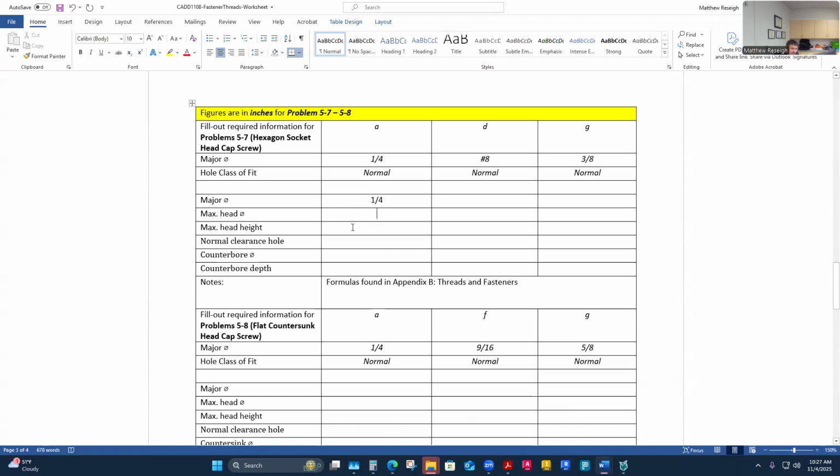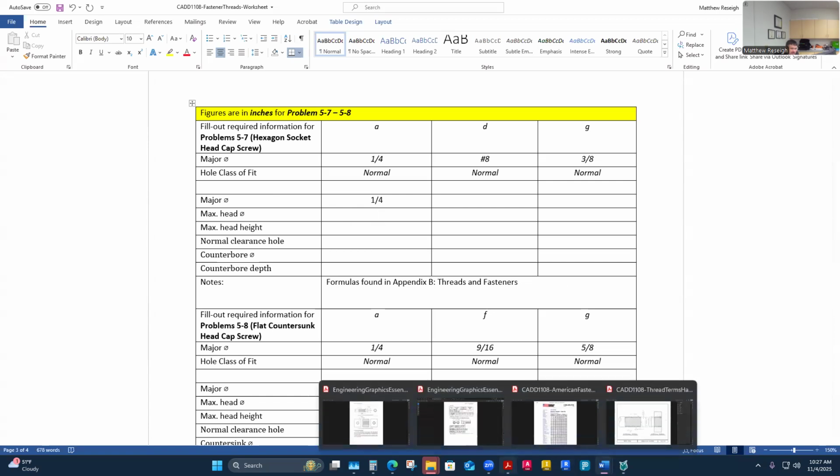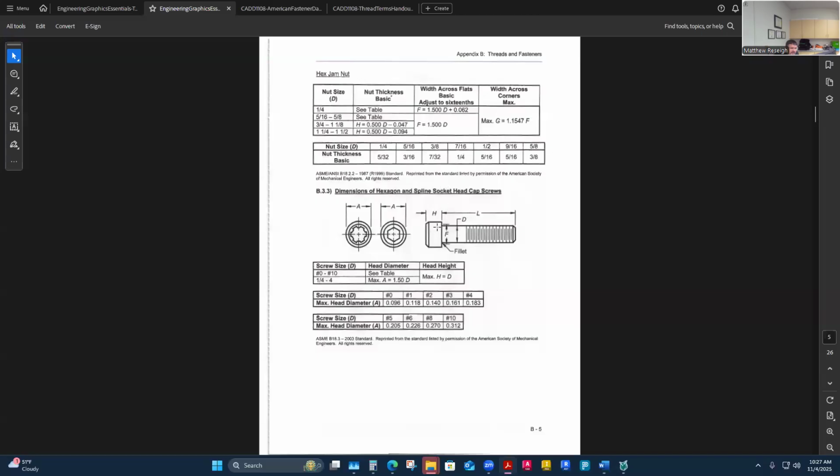These types of screws can be inset, so let me talk about how they might be used. A lot of the time these go into a counterbore, and we've drawn and notated a few counterbores on our drawings already. This type of screw might fit into a counterbore, where all of this is going to be doing the work. It might be sunken into the material, so that when my fastener is doing its work, the head is flush to the surface.